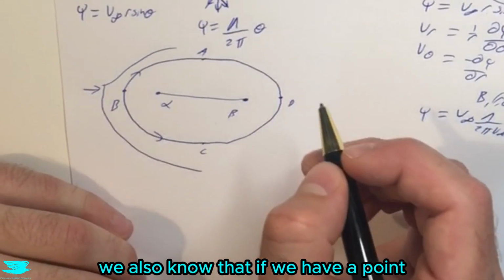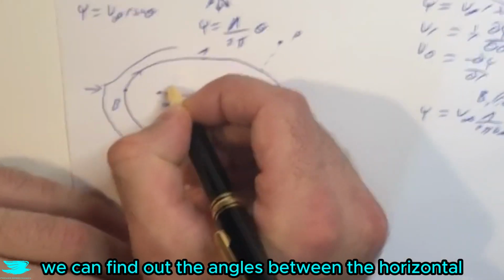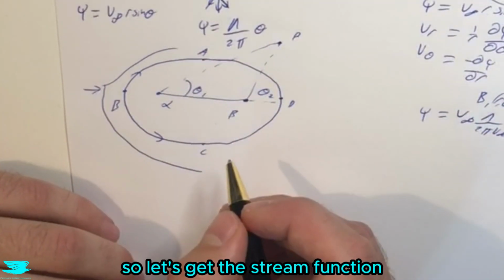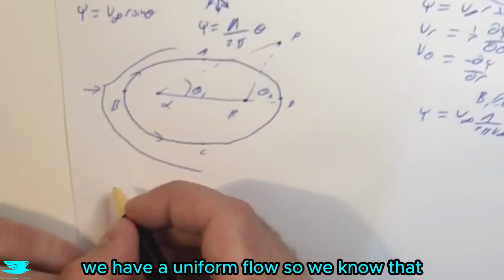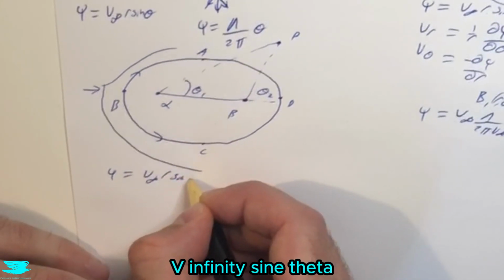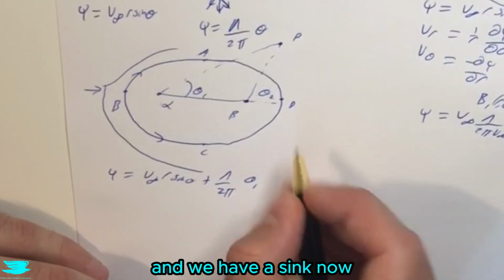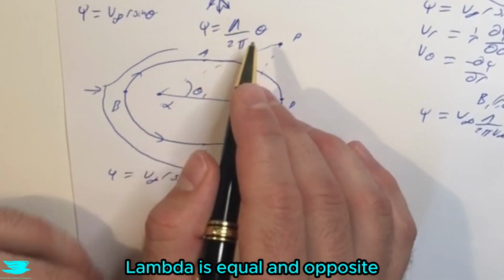So from our other videos, we also know that if we have a point, let's say P here, we can find out the angles between the horizontal, which is θ1, and horizontal here, θ2. So let's get the stream function for this entire setup. We have a uniform flow, so we know that we have to add that to the stream function, r sine theta. We have the source, so let's add that as well, lambda on 2 pi θ1, and we have the sink.